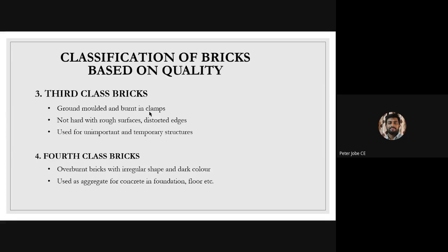So it will be difficult for us to use them in wall construction, and hence we'll break them apart and use them as aggregate for concrete in foundations and some flooring purposes, where the properties of a brick are not actually required. There will be times when we need to use it in concrete while doing a foundation or a floor. So we'll break all these fourth class bricks into small parts, and then we will add them into concrete.